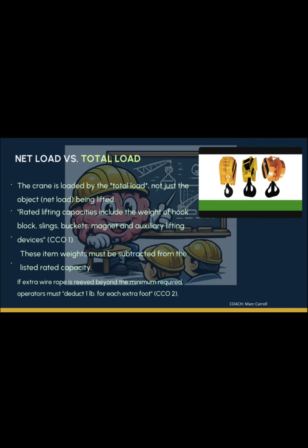Now, when we install the jib on the boom tip, we have to remember that jib charts are based on structural stability. If your boom is not structurally sound, you will have a catastrophic boom failure, a potentially dynamic unloading of the load, and killing somebody.